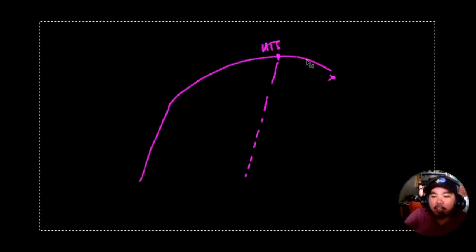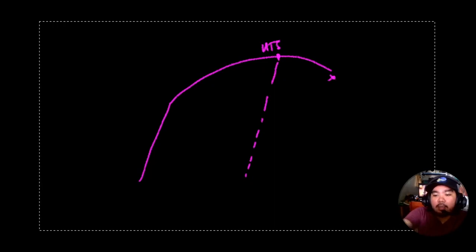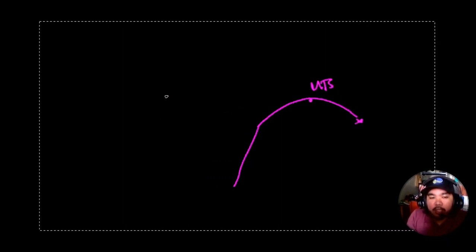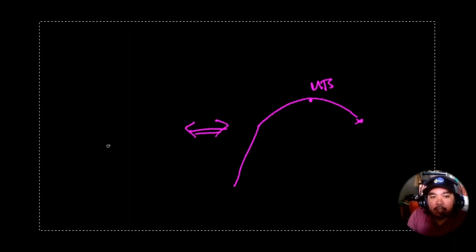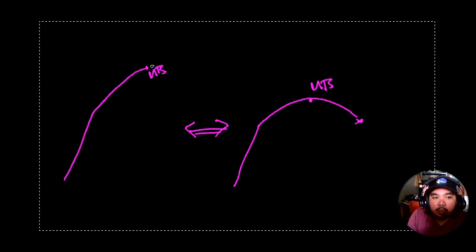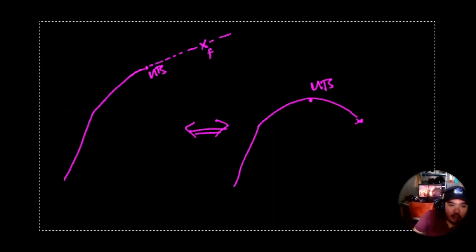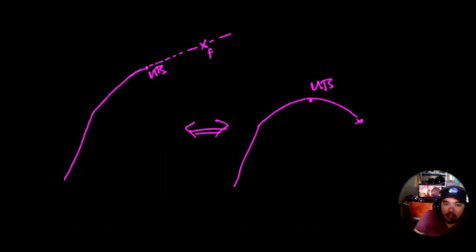And in fact, in the true stress strain diagram, when we do a true stress strain diagram, and I'll just do this again, if you have something like this, this is the UTS. In stress, if you convert this to a true stress strain diagram, you actually have it only up to the UTS. Past the UTS, this is just a modeled behavior, up to the fracture point. Modeled in the sense that whatever the slope is here, it takes that and projects it outwards, like this. Okay, so I hope I answered your question adequately.